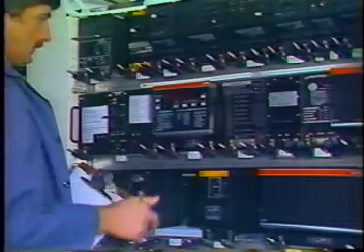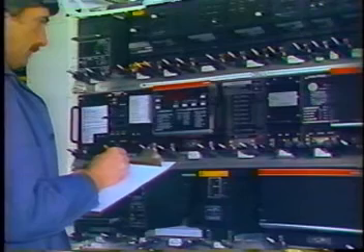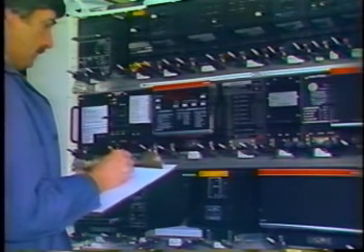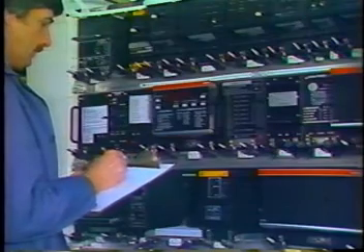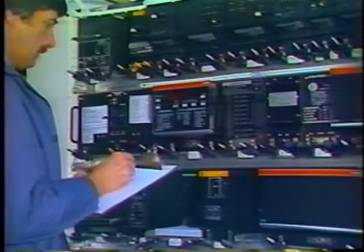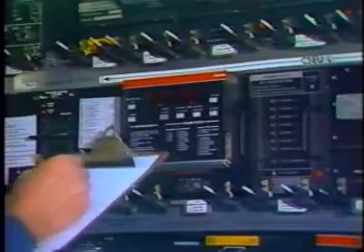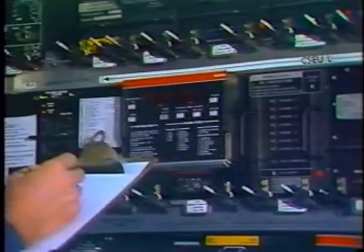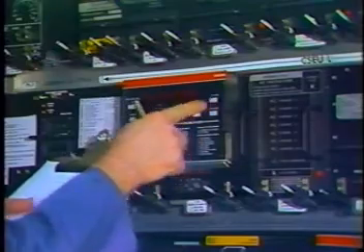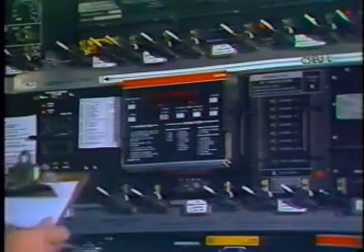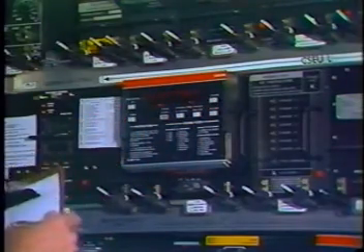An additional major component associated with the Autopilot Flight Director system is the Maintenance Control and Display Panel, or MCDP, located in the Main Equipment Center. The MCDP combines flight fault storage and ground test functions for the AFDS, as well as for the flight management and thrust management systems.